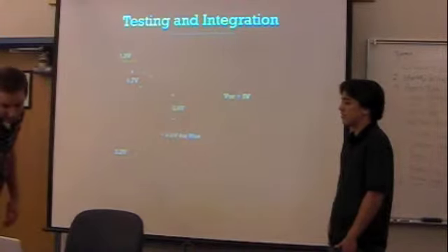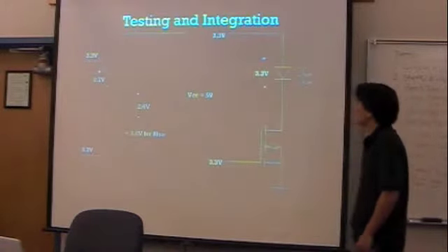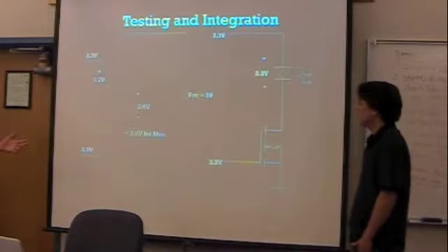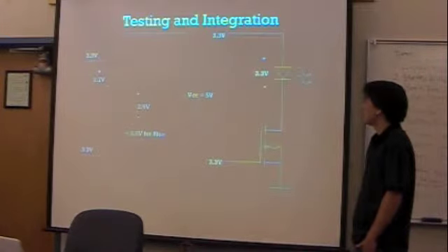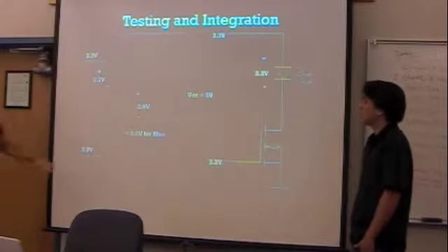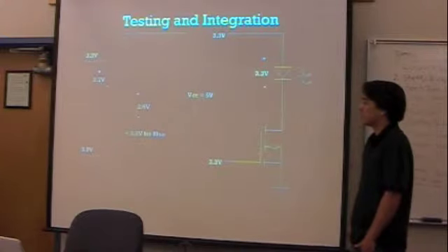So it was back to the drawing board, and we came up with a new design using the MOSFET, which doesn't have a drop nearly across it. You just have to supply a gate voltage large enough, and then it behaves just like a switch. So we got rid of the top one and just connected it straight into the Nexus board. So now you have 3.3, and they're plenty bright now. And this eliminated all these BJTs, so now we only have 4 MOSFETs, and everything else connects right to the Nexus board. So with the reduction in components, we were able to implement the 4x4 and exceed our expectations.